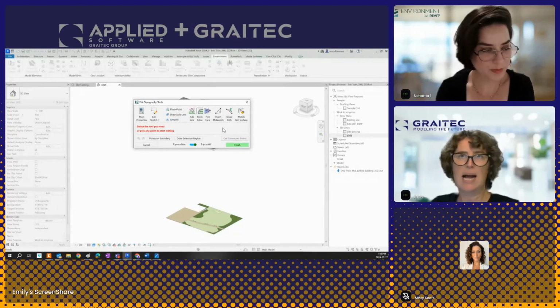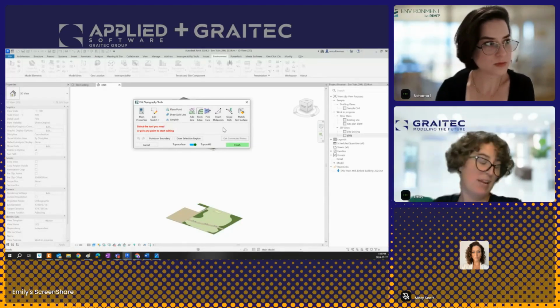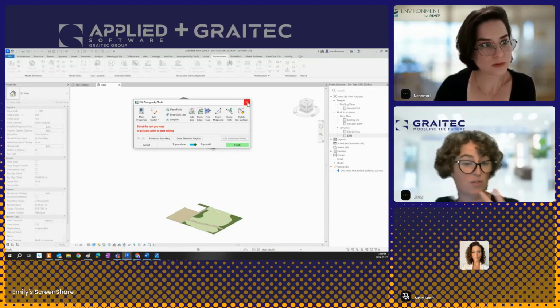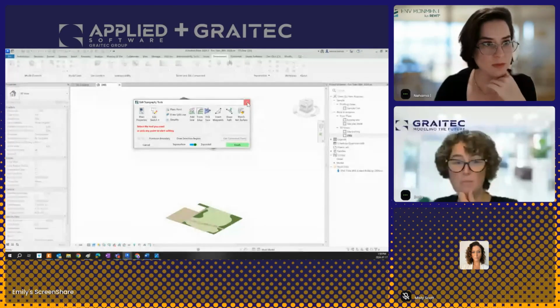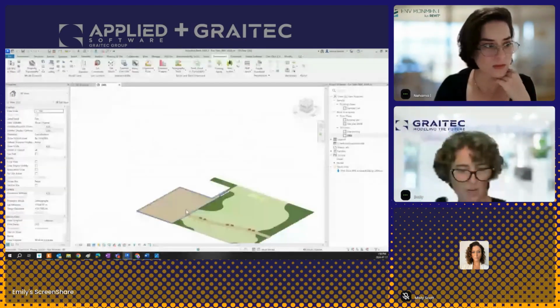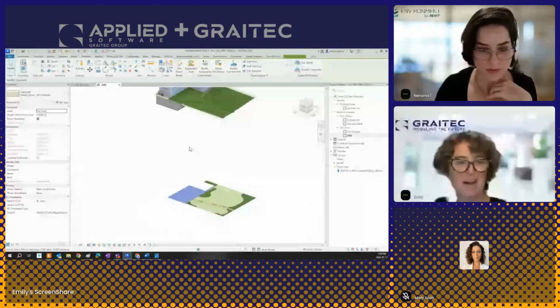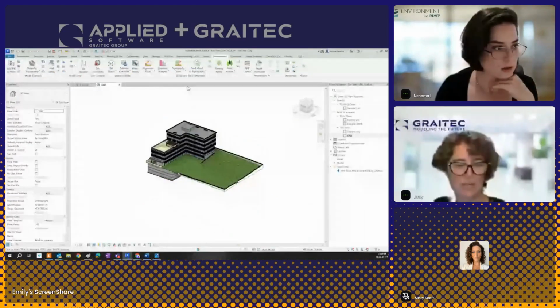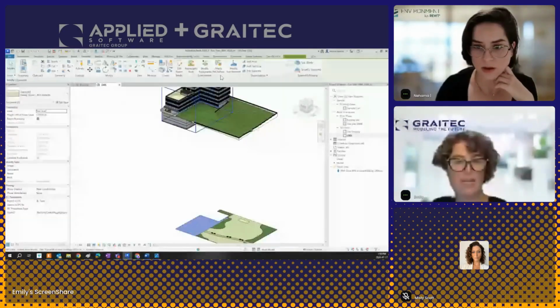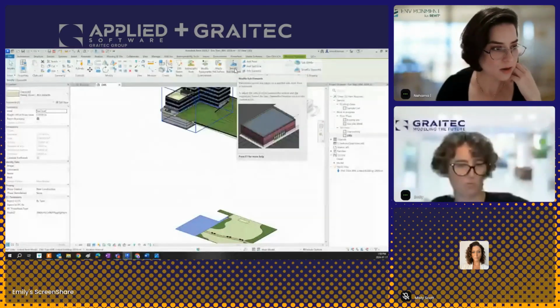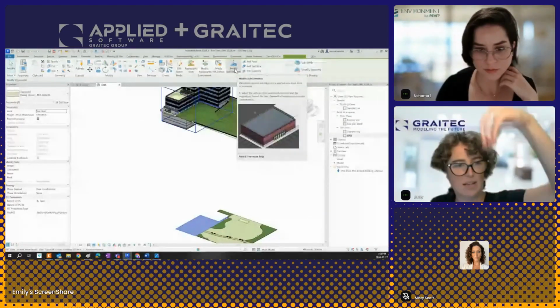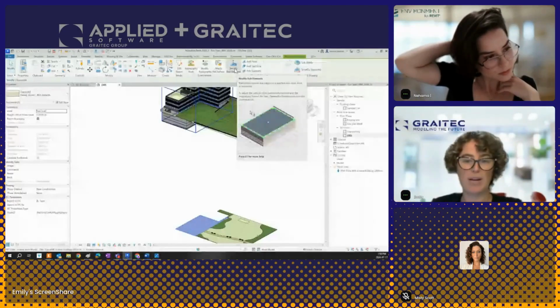Yeah. And when it comes to topo solid, if anybody did any landscape work using floors as your hardscape or softscape surfaces, you might have used the Modify Sub-Elements tools to create a point, create a slope. If you've made a roof or a floor and you need a drain in it, you can slope to that point.